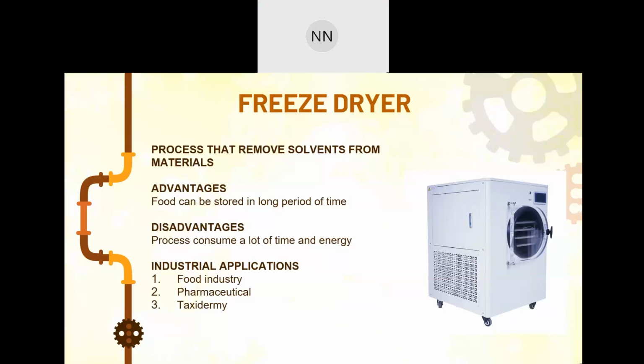The freeze dryer's cold condenser provides a surface for water vapor to adhere and solidify, while the condenser also protects the vacuum pump from water vapor. The last phase is known as secondary drying or the adsorption phase. During this phase, the ionically bound water molecules are removed, and this is done by raising the temperature higher than in the primary drying phase. That's all.